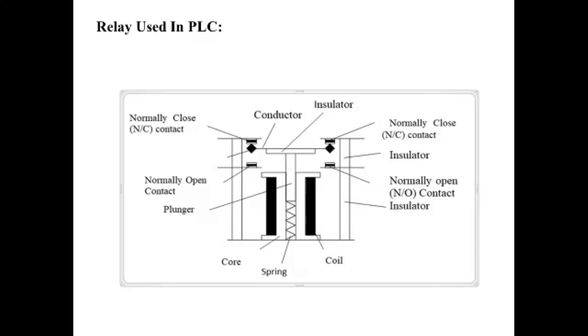Also, the time on or delay on timer, that is the TON relay, is used in PLC systems. When an on timer is installed in the circuit, which is the ladder circuit, the user adjusts the control on the relay for the desired time delay.